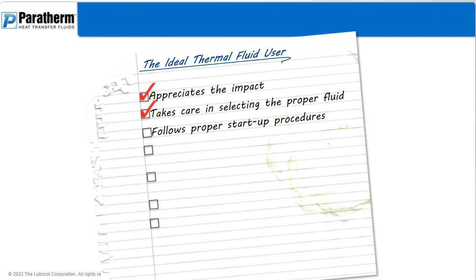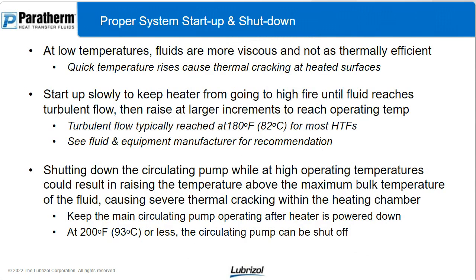So what do we mean by proper startup? First and foremost, proper startup of a system, you want to make sure, and it's not mentioned on this slide, and I apologize, but you want to make sure you have a clean system to start with. So whether you drained a system and refilled, or you maybe had a brand new system commissioned, and for some reason someone decided to use a cleaning agent beforehand, you want to make sure there's no moisture in that system. There was nothing water-based introduced into it. So that's really important. Starting up with a clean system is really important.